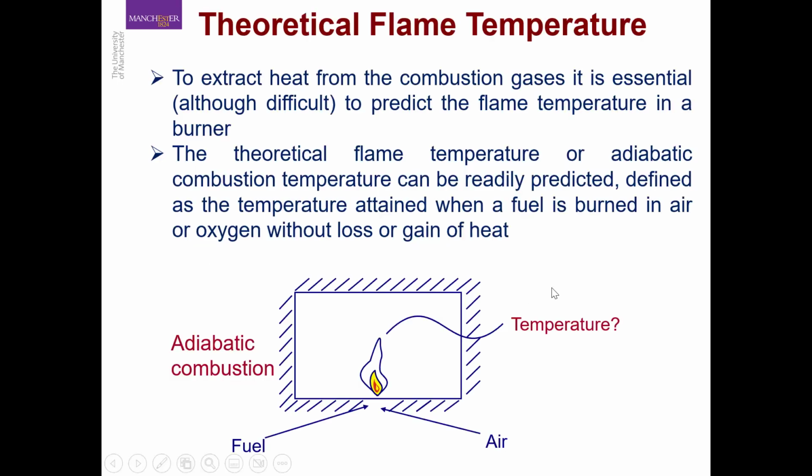Okay, so when we perform a heat balance around a furnace, this heat balance can be used to determine the actual flame temperature, and the actual flame temperature is a function of the calorific value of the fuel, the construction and the type of the burner, the heat losses due to incomplete combustion or due to the loss to the ambient, or due to dissociation of the product or the flue gases.